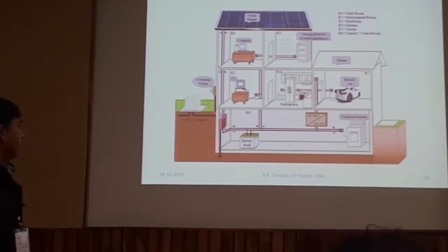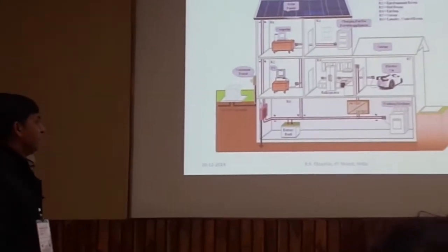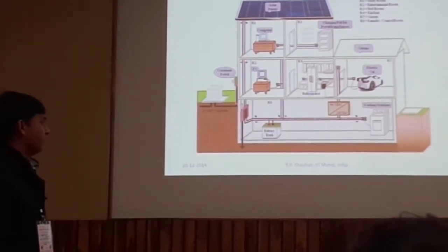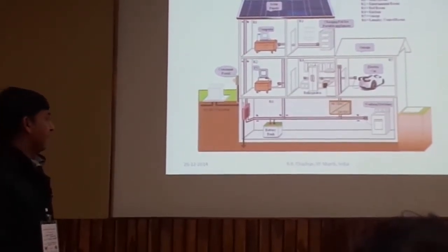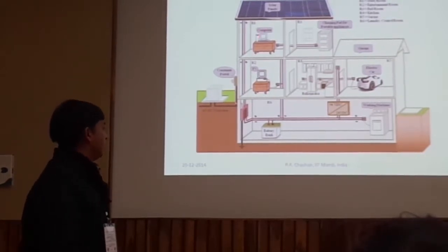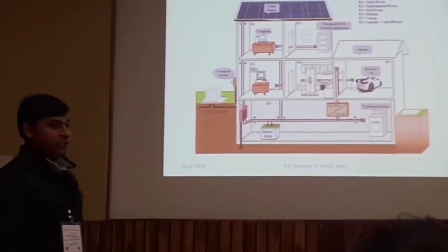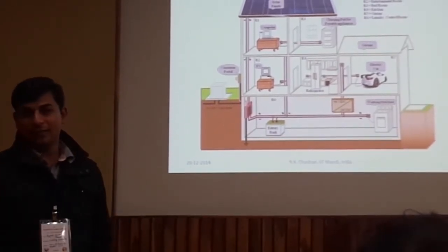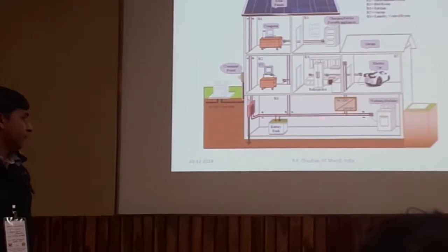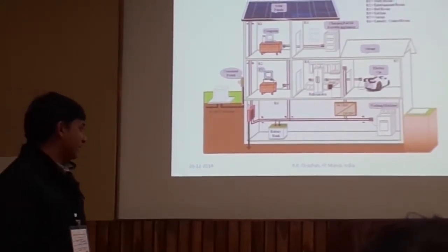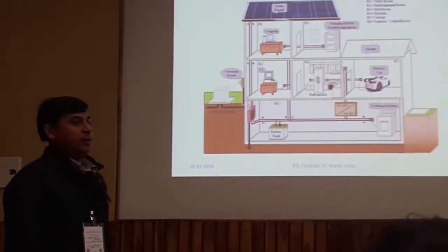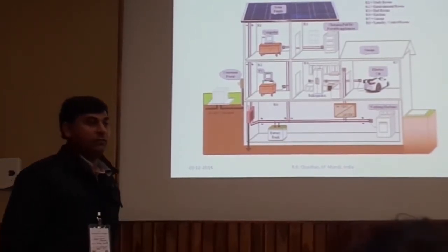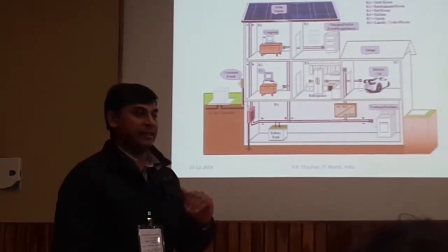And here we can see that there is no need to connect the solar panel with an inverter or a converter. It means we are replacing this converter, and on the load end, the computer and TV are using DC supplies. It means we do not need to use internal or external AC to DC converters here. I use only one DC to DC boost converter here for high rating loads, to minimize the current inside the lines.